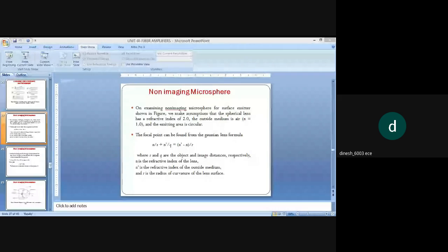since the angular output is greater. So the laser will have an angular output distribution greater than the fiber axis angle. The emitting area is much smaller than the fiber core. So we can use a spherical lens, a cylindrical lens, or optical fiber tapers. Coupling efficiency between the fiber and the edge emitting laser diodes.